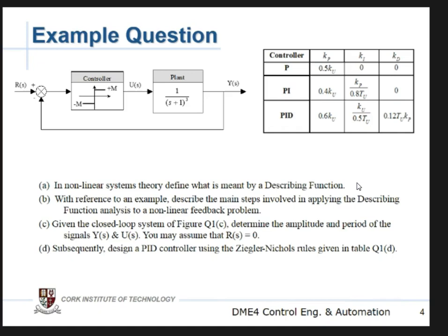So this is our simple nonlinearity, with high frequency elements here. This low pass filter chops them out, and therefore we have a single frequency going in and a single frequency coming out, and therefore it's possible to linearize it, because one of the definitions of a linear system is one frequency in and one frequency out.